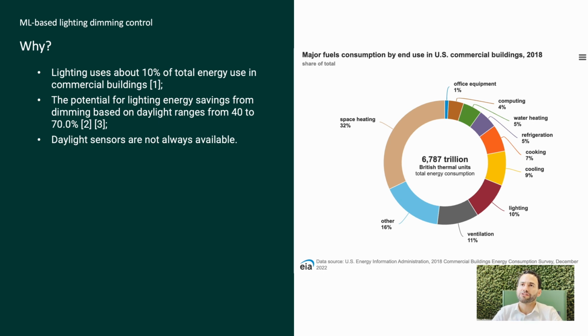Also, daylight sensors are not easily available in buildings. They are usually in buildings with a lot of technology, but they also sometimes are not very well calibrated. So yeah, there are some issues when we're talking about daylight sensors in typical commercial buildings.